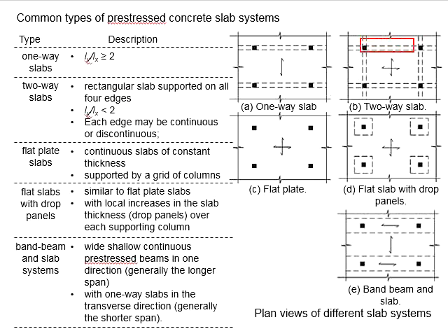That means the difference between the longer span and the shorter span is not that significant. Due to the existence of the adjacent slab, there will be conditions for the continuous and discontinuous edge. This to some degree will affect the fixed end moment at the edge of the slab.